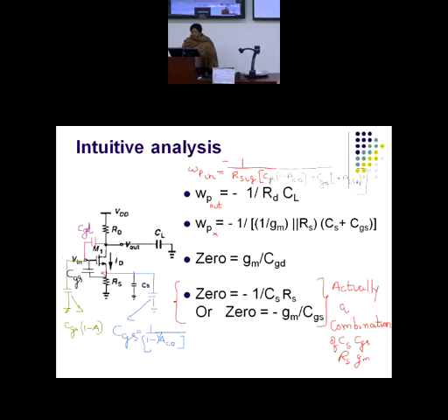Clear? So RD, and the net capacitance at the node Vout. It will be all parasitics, a component of CGD and CL added together. Okay. So I am writing CL. Why? I may be assuming CL is much dominating over other parasitics and other components of the capacitive loading. But then you should understand that when you write more accurately, all those effects will have to be added together. Fine.